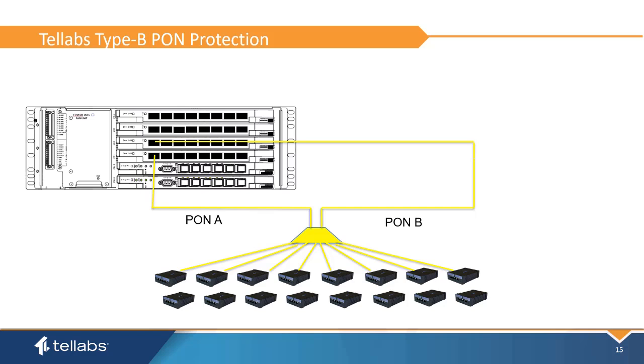Intra-OLT PON protection is a PON protection group on two ports on different PON cards within the same OLT. This is typically used for cost savings. It should be noted that in this configuration, some OLT hardware in the path is not redundant.